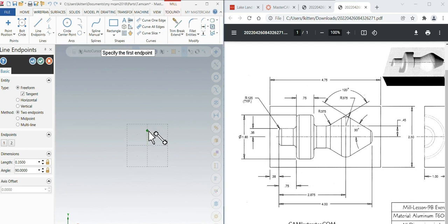So now pick on, we're still in the line mode here, okay? So it says specify first endpoint again. Pick on the left or the top of that line. We're going to draw the one over here. Now, how do you go back? Zoom out a little more. Hit undo. And hit undo. Yeah, so if you mess anything up, you can always pick the object and hit the delete key on your keyboard. There's an undo here. You can always start again, okay? So if you mess anything up, just undo it and start again, or hit escape and delete what's wrong and start again.